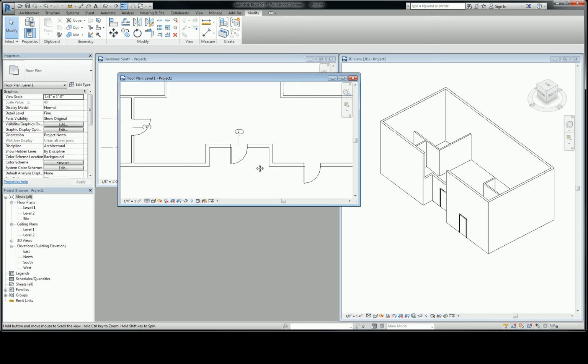All right, there is one other thing. I'm sorry, you said generic was drywall, studs, plaster? This is purely generic. It's just like a mass. It's like you modeled it in Rhino and just extruded it. So does it tell us somewhere what that wall is made of? Does it tell us it has plaster this thick, studs this thick? Yes, it will. I didn't want to get there today. I want to do that next week, and we're going to go through setting up assemblies very thoroughly. This one does not have an assembly. I mean, it does. It has one layer, and it's just generic.